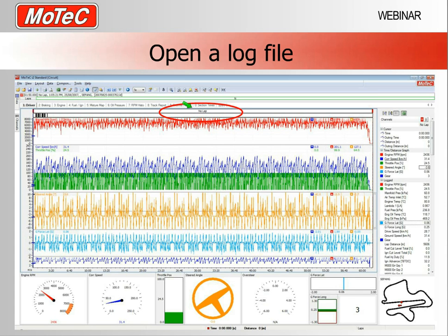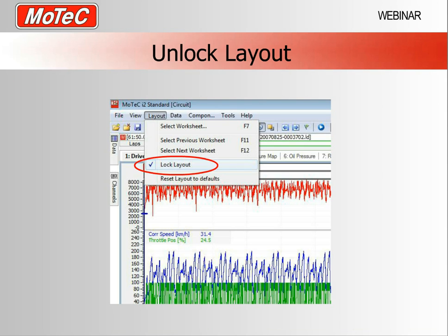If you forget to set your latitudes and your longitudes, you will also have this same problem where you won't be able to see any laps. So how do I put lap times in here now, and how do I find my GPS latitude and my GPS longitude so that I get lap times the next time I go out and run the car?